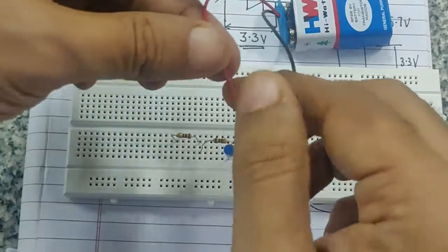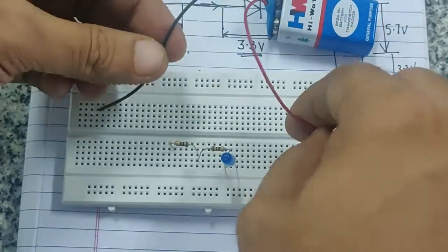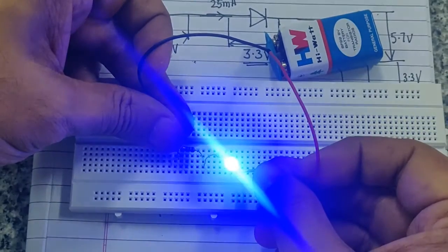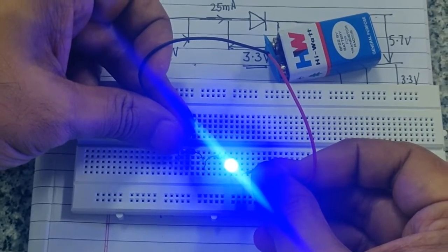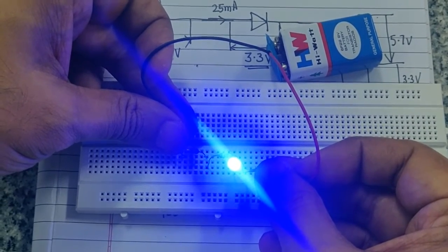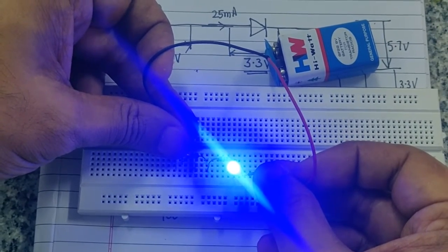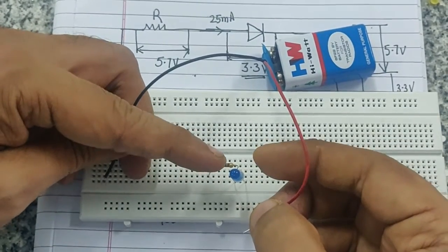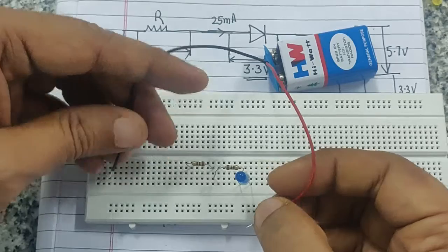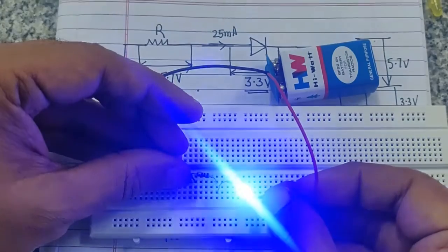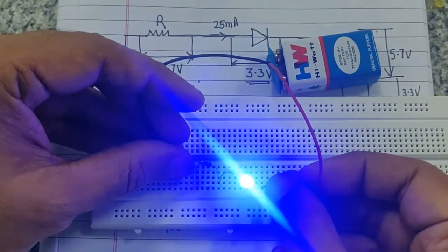In an LED you have to have the right polarity. So you give this, and here you go. The LED is glowing, and this time it is not burning up, because you have about 5.7 volts dropped by these two resistors, or maybe a little less since we are using 200 ohms instead of 228, and the rest is across the LED.